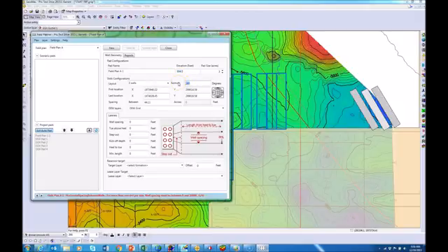The azimuth is 180 degrees, and from the drilling department they give me the well spacing of 665 feet, step out of 150 feet, kickoff depth of 3,500 feet, heel to toe 10,000 feet with a minimum length of 1,000. My target layer is the Barnett target surface, and my lease layer buffer is this Anadarko Leases 2. Let's update the layer.